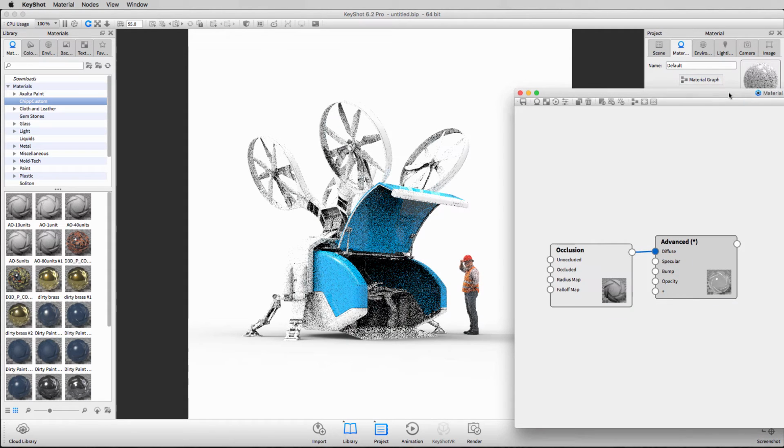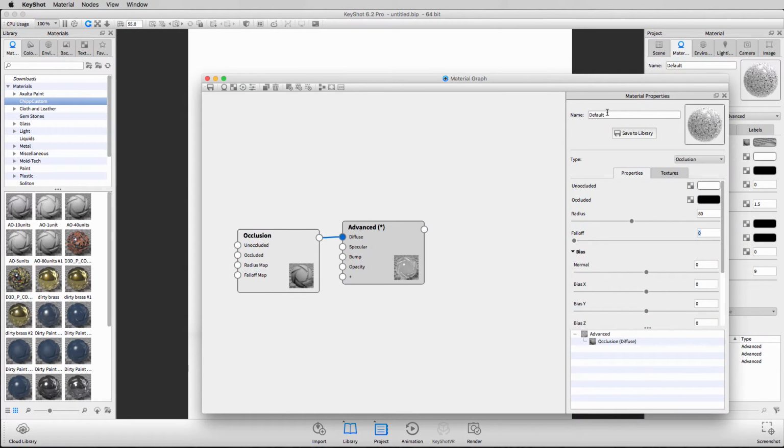Okay. And when I do that, notice it gets a lot darker in here, right? So if I take it down to 0, it's a little bit lighter, right? So it's basically making the darker areas stand out just a little bit more. So I make it 200. Look, it's really dark. So I want to make it about 80, and that's going to work. And that's going to be the material that I use. I will call it ambient occlusion, AO, and we'll save that.